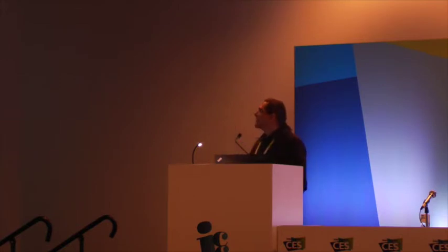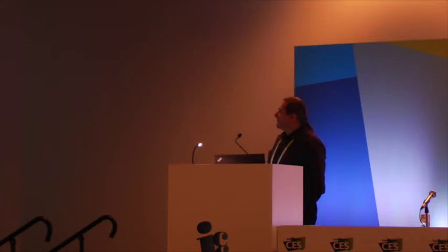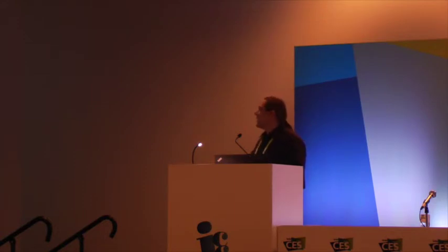that are available. But even this upmixer expects that the output speakers are located regarding the ITU standard. So the input signals are regarded to have ITU standard, as I showed before, plus minus 30 degrees, whereas it is expected that the output speakers are also arranged regarding the standard. So if you do not have this standard, which is typically the case, then this upmixer is also not working perfectly well. So this problem of room equalization still remains.